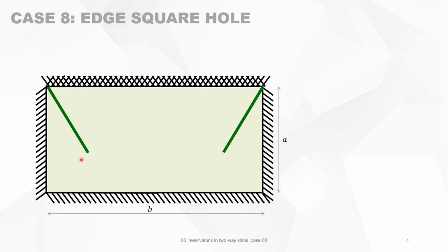We draw the line. This is the same 60 degrees, 30 degrees, on the bottom 45, 45 degrees, and then we make the connection with the yield line. Of course, there's also a yield line at the fixed end. We assume that the plastic bending moment in the field is the same as the plastic bending moment on top of the slab.